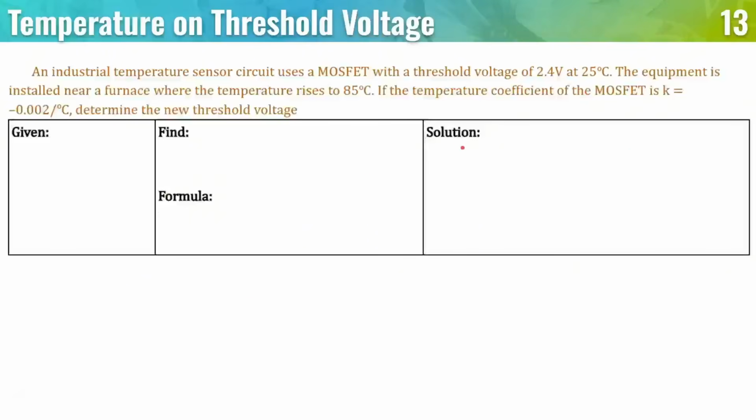It is better to compute it. The reason is that of the two textbooks we are using for our course, one says room temperature is 26 and one assumes room temperature is 27. And when we compute for it, it's not going to be exactly 26 millivolts. It's going to be something like 25.8, 25.9, etc. So let's show the computation.